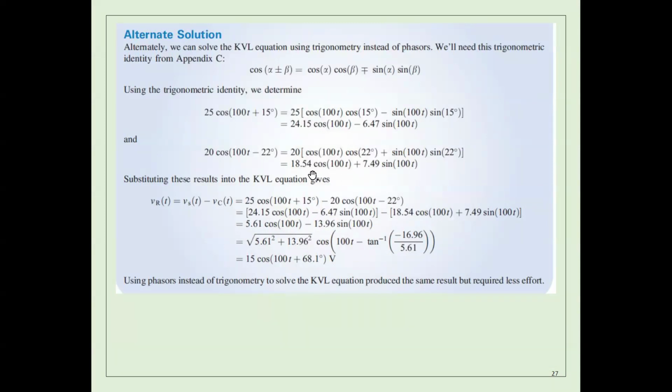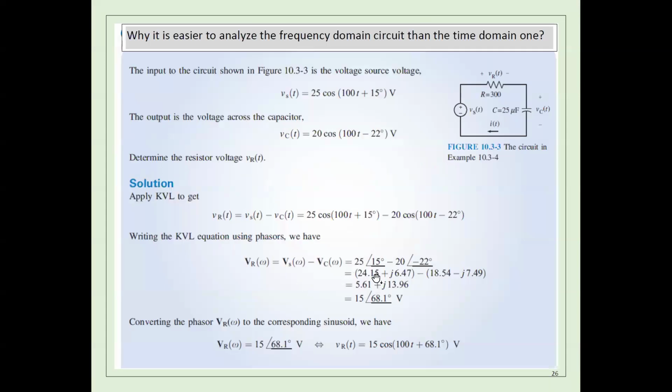Anyway, you can see it will be too complicated if you do something simple like subtraction in the time domain. That's why it will be much easier in the complex domain. If I want to do this subtraction in the complex domain, you have to convert the first one to the complex domain. To do the conversion, I take root 5, I take 15, and no omega t. Same thing here, this one is 20, this one minus 20.